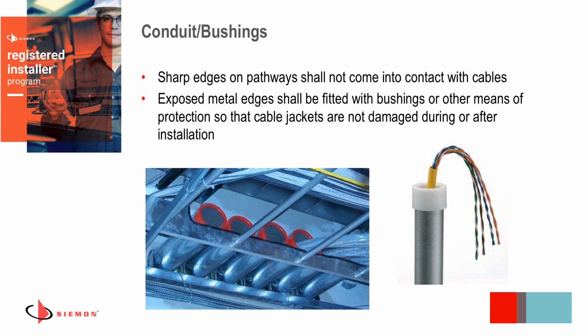If you're installing conduits into a telecommunications room, or maybe it's a penetration within a wall coming from outside to inside, it's important that any edges on those conduit systems have a bushing, again, to protect the cables. These cables, you have an investment in the materials as well as the time to install these, and you don't want to see them damaged as a result of not ensuring that the pathways are properly protected from damaging these cables.